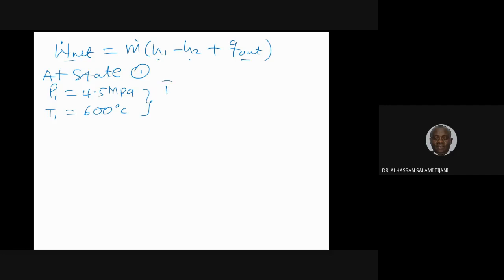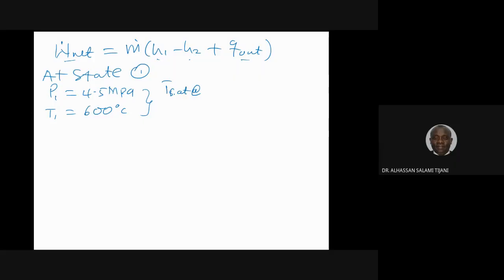Okay, so T1, from the table, T saturation at 4.5 megapascal equals 257.44 degrees Celsius. T1 is greater than this temperature, T saturation. So it means the fluid is superheated. Okay, so T1 is greater than T saturation